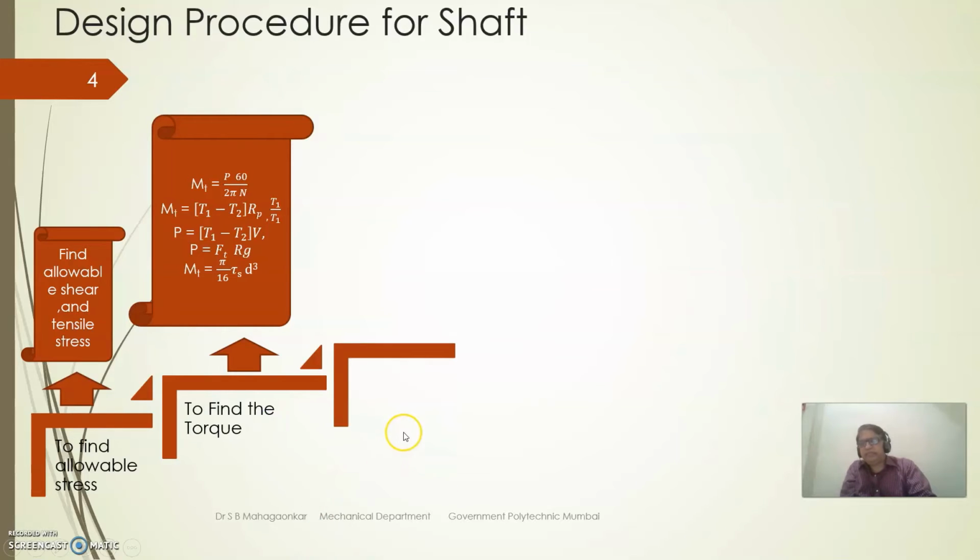And now the third step, tensions in the belt. That is vertical tension, and then the second one is horizontal tension. Normally the design problem is very simple. We draw it first, we go for only vertical loads and the vertical moment diagram, and then horizontal loads and the horizontal moment diagram.